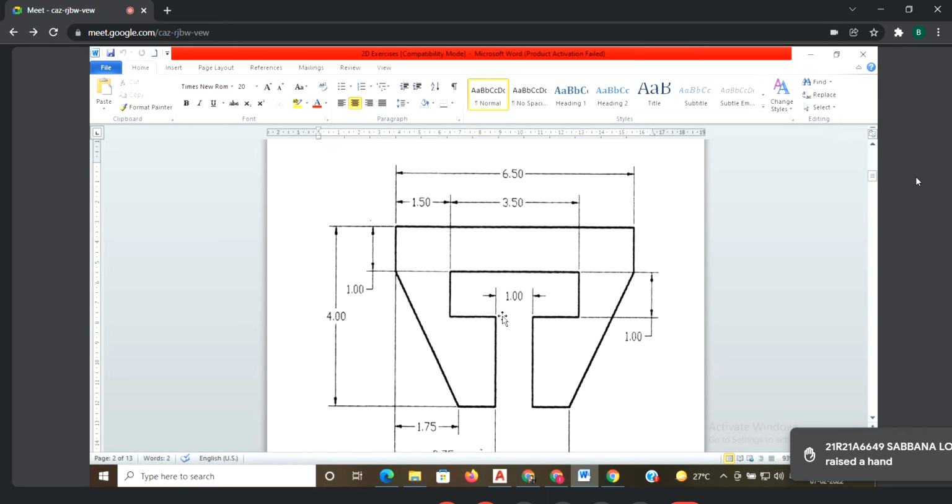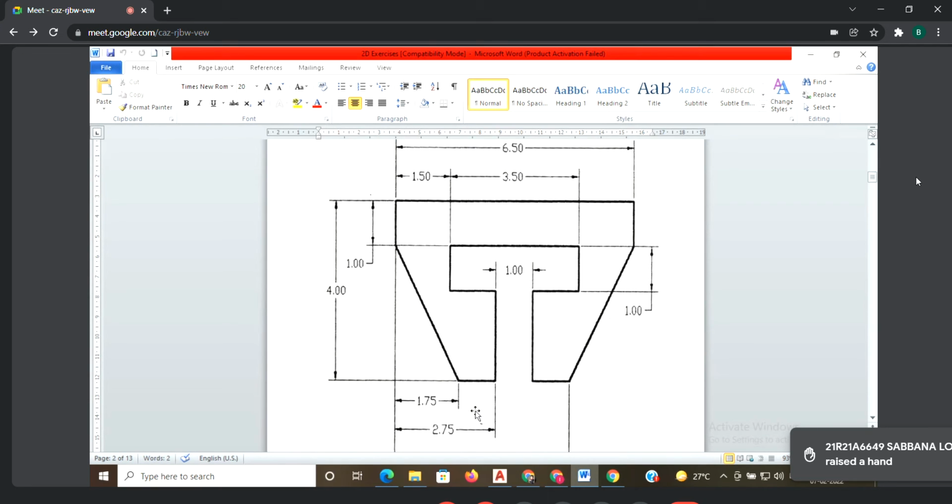This way you have to find out the values, find out the dimensions initially. That is the use of your drawing. Meaning if you spend 5 minutes, this is the use. Suppose without reading anything, I start from this corner, from the lower left corner. Total height is 40. Total length here is 17.5. First I will start, then I will get stuck here. How much is this one? I don't know. Again, I have to go for subtraction, 27.5 minus 17.5. How much? There you are finding it. Instead of that, on the question paper, if you read the dimensions and draw your dimensions